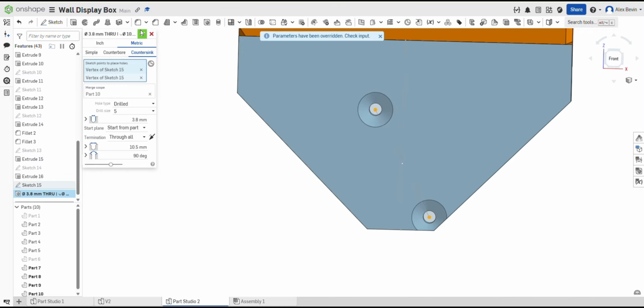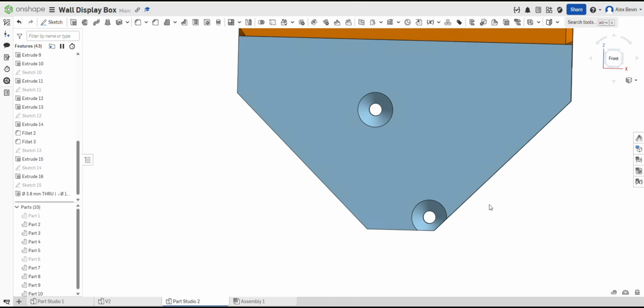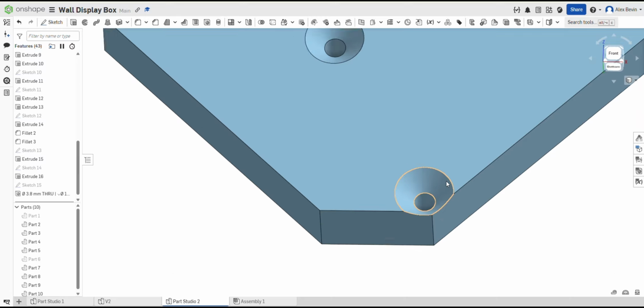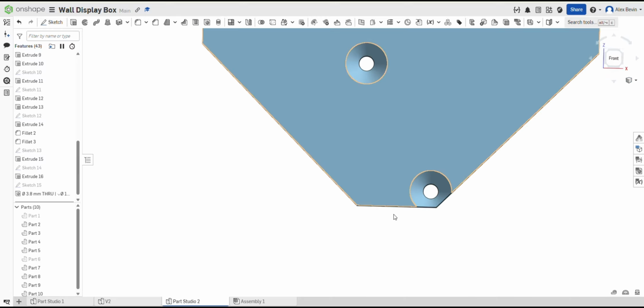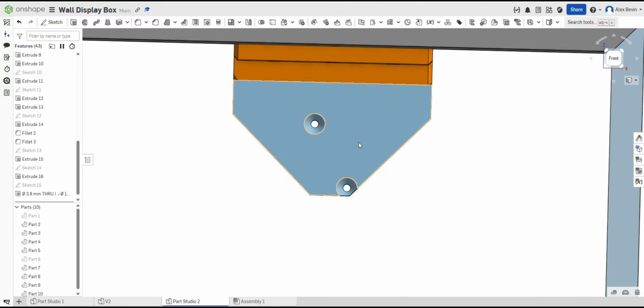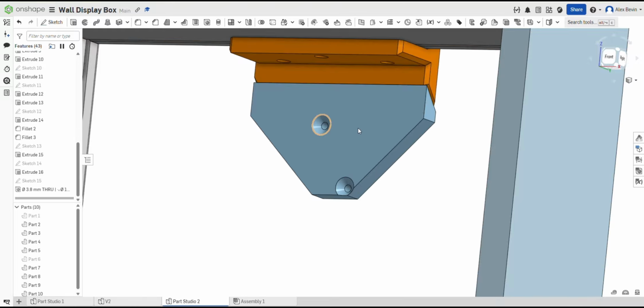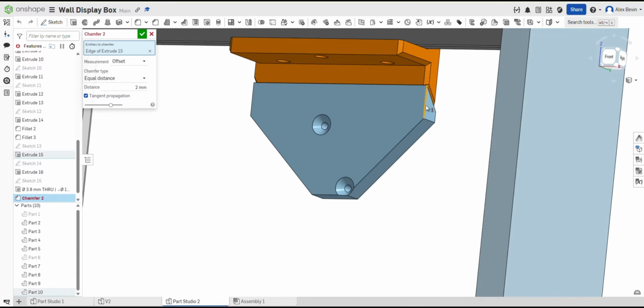Section E. Useful 3D printing filler. Quick printing tip while we're here. For cleats like this, print strength depends heavily on orientation. If you print it so the layer lines run across the thin sections, it can snap. If you rotate it so the layers support the load path, it usually lasts longer. And if the fit is tight in real life, don't redesign straight away. Try a tiny chamfer or sand the contact surface first.